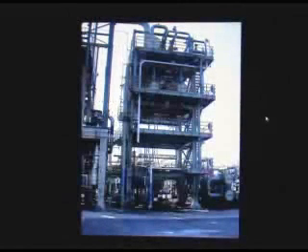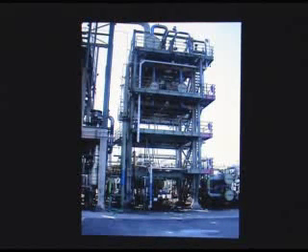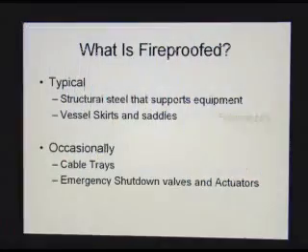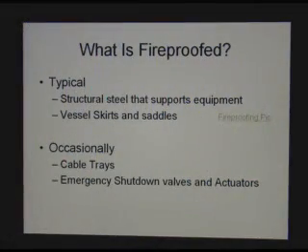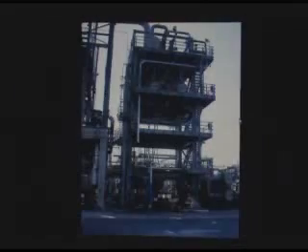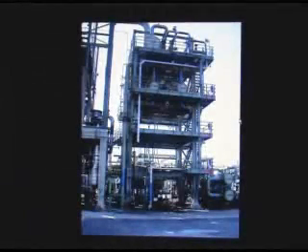They are fireproofed because this equipment up on top here and here is fire potential equipment. However, these platforms here are not needed in the fire case to keep the integrity of the structure. Therefore, it's not fireproofed.